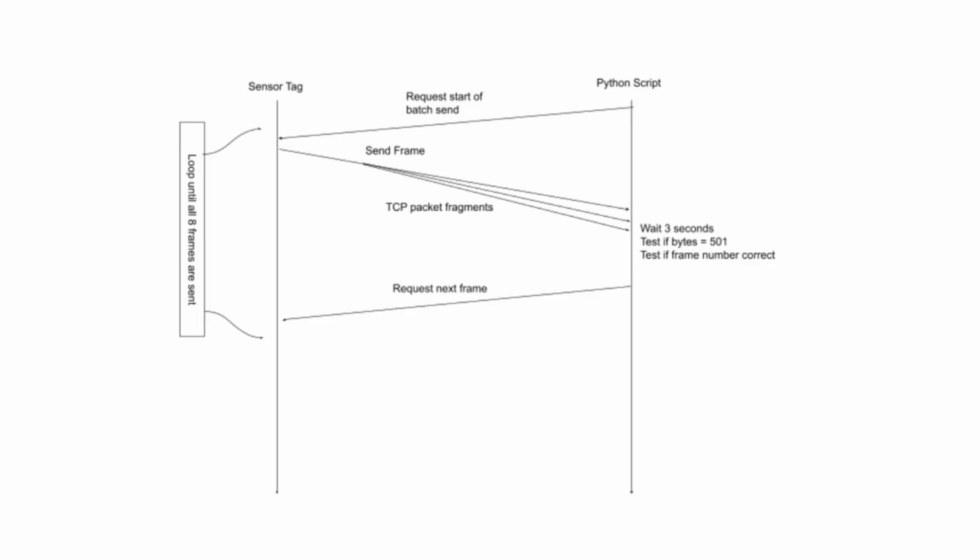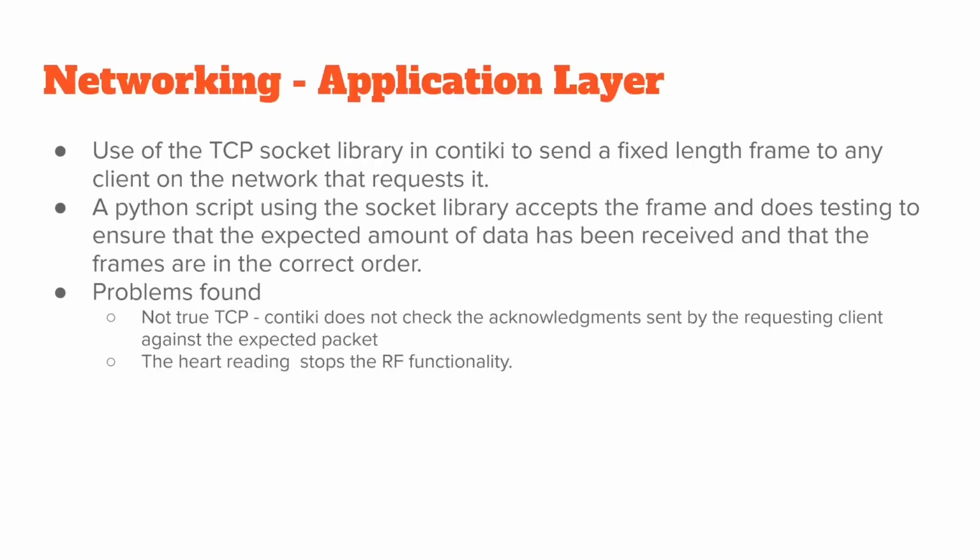And we were fairly successful. We're able to send a full 4 kilobytes back in about 15 seconds, which isn't fantastic, but is what it is. Once the Python script had received the 4,000 bytes, it would then check each of the frames, drop those single bytes from the first part of the frame, and then with those 4,000 bytes, take every 2 and merge them back together into unsigned bits, and then output them to a CSV, which was then fed into the SVM.